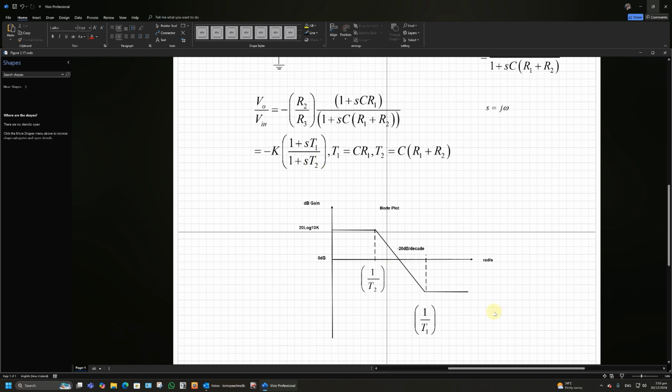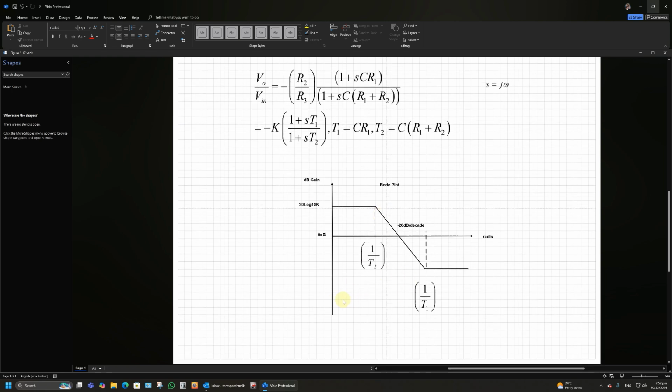If you're interested in what we use such a circuit for, probably a lot of things, but in control, which was my area, it was used rather as a phase lag compensator. If you draw the phase, which I haven't got in here, it starts at 0, and then it goes down to some negative value, which I could talk about, I'm not going to, and then it goes back up again, back to 0. So it just dips down negative and back up again. And a negative phase isn't really a good thing at all in a control system, because it reduces phase margin.